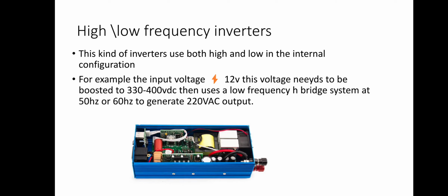But when there is very good protection, your inverter will be secured and it will shut down. But the disadvantage of this one, as I've said, is that if there is a short circuit, most times it directly affects the MOSFET system. So this is one of the disadvantages of this inverter. But one of the advantages, again, is that it is a very lightweight inverter and it is affordable. It is cheaper than the transformer based inverter.